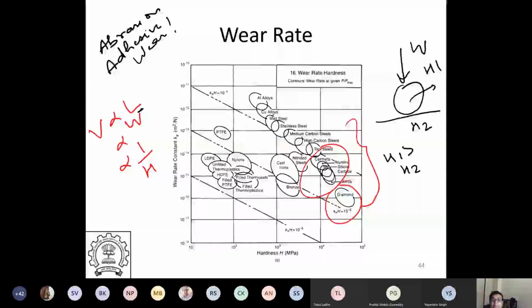But there is another case of adhesive wear where you write with a pencil on a paper, right? Which one is harder, the graphite lead or the paper? If you measure the hardness. Sir, graphite is harder, obviously. Right, but then it wears out on paper, right? So that's a good answer. What I'm saying is the mechanism of wear can happen even with the harder material wearing also. That's what I wanted to give you as the moral of the story.